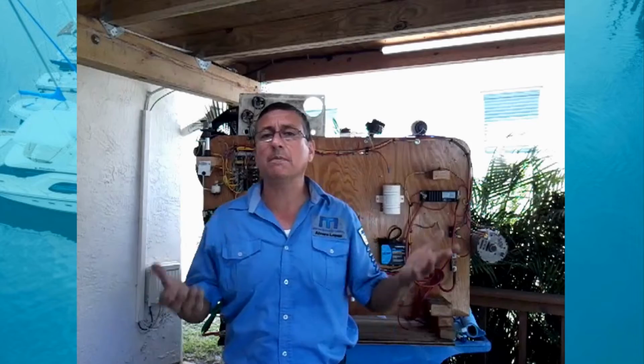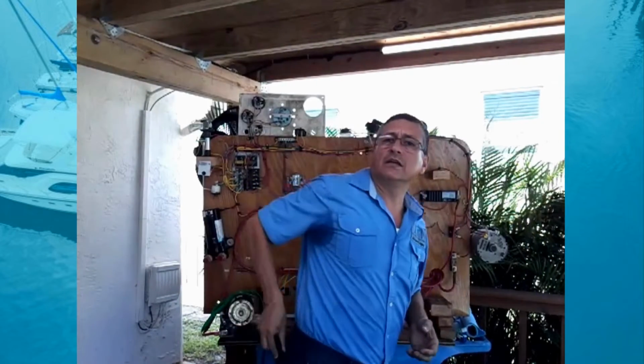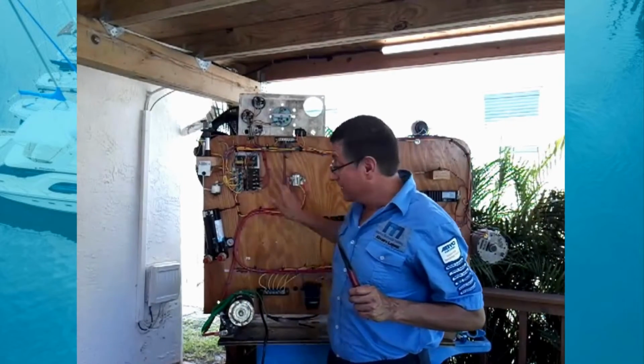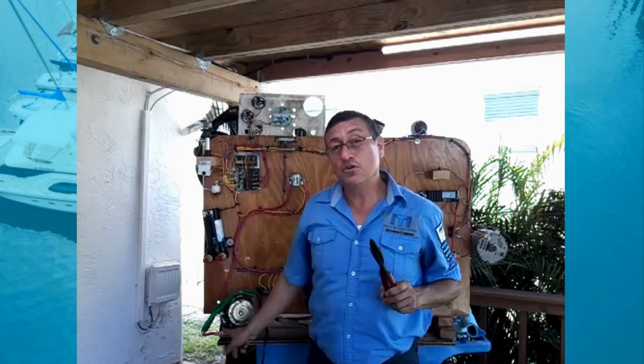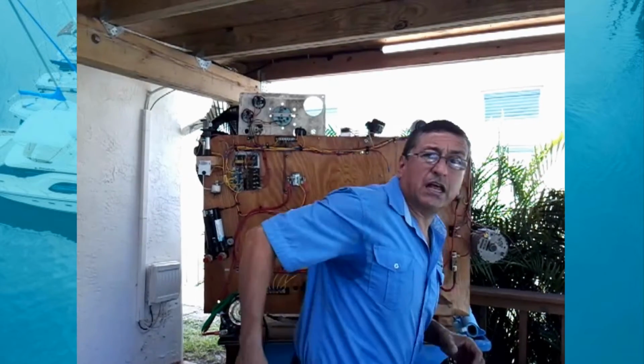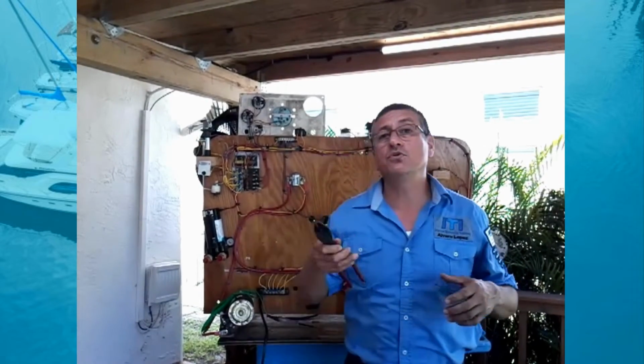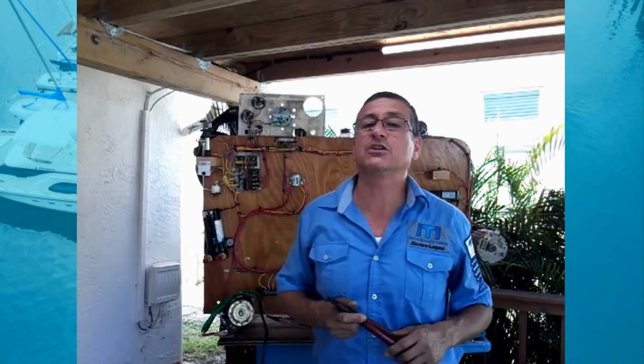If you are working on other equipment, air conditioning equipment, or installing bilge pumps, and you have tools in your pocket like this, and you don't have relays like this, you have constant power in this terminal. If you are working and you approximate the tool to this point, you can produce a short, you can produce a spark, and you can produce an explosion.